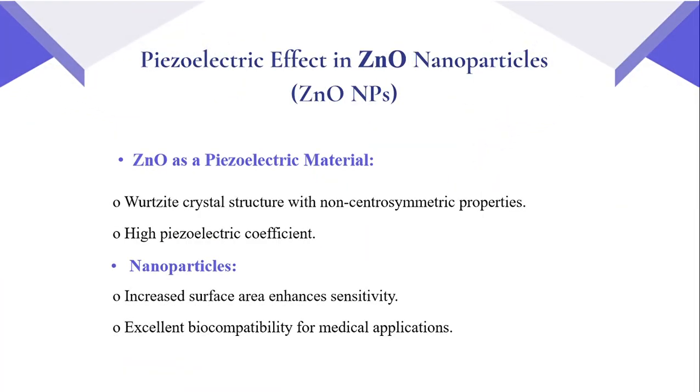Here are some key points. Piezoelectric effect in zinc oxide nanoparticles is mainly because of its wurtzite crystal structure with non-centrosymmetric properties and its high piezoelectric coefficient, and the nanoparticles result in a decreased size and increased surface area, which enhances sensitivity. It means basically when we convert a bulk material into nanoparticles, the size decreases, and when size decreases, its surface area increases, which enhances the sensitivity, and it has excellent biocompatibility for medical applications.